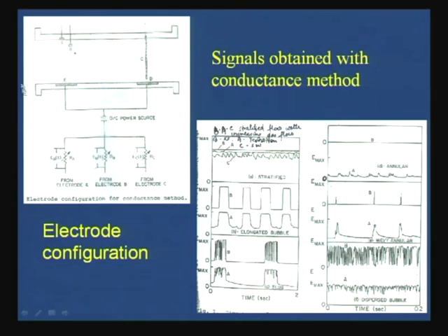Okay. So, depending upon the design of the probe that we have done, we can actually identify all the flow patterns that we can encounter in a horizontal gas liquid system, and importantly we can actually differentiate between the transitions, which is very important. Identifying transitions is extremely important, like it is very difficult to differentiate between slug and bubbly flow.